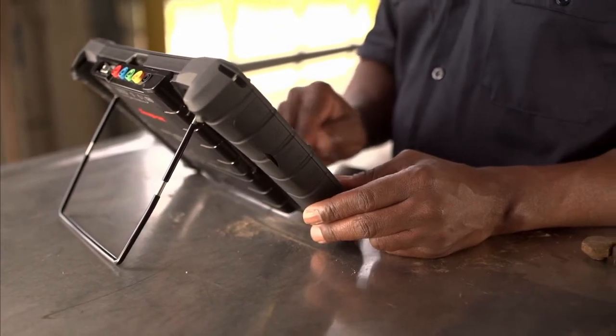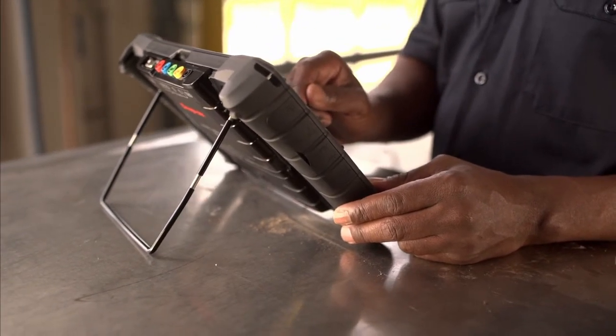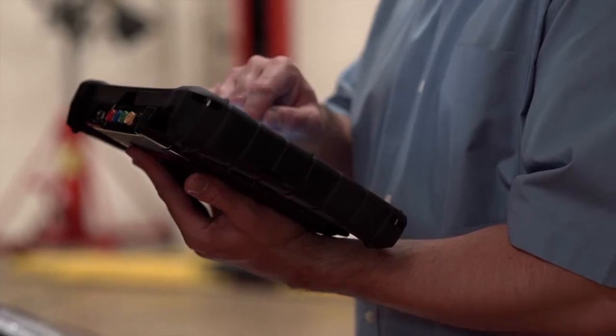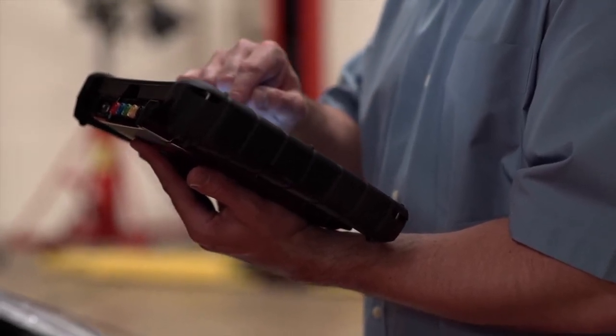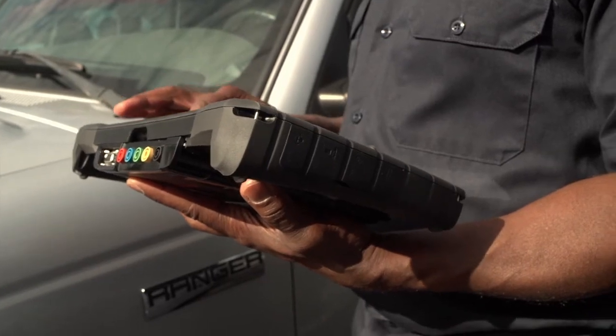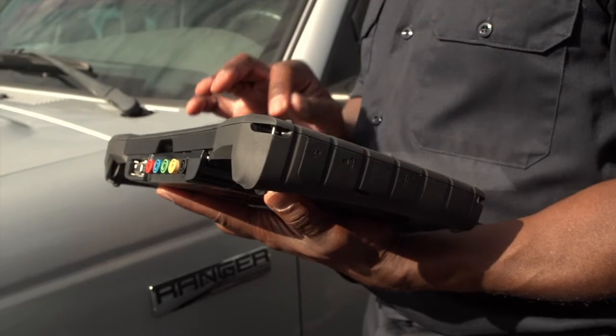The graphing multimeter and lab scope are powerful diagnostic tools that give you the ability to directly test vehicle components to verify faulty components before replacement. To avoid damaging the meter, never attempt to measure more than the meter's rated capacity.